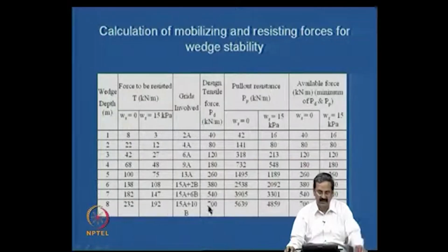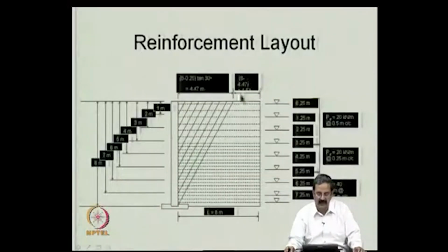Based on this you try to come out with some configuration, as I just mentioned, for example 0.25 spacing, some sort of spacing you can provide, and you can also provide these materials like this. This is that failure wedge I was telling about, 45 minus phi by 2. This simple Excel program calculation one can do. Length is also 6 meters. This is a simple structure, right.